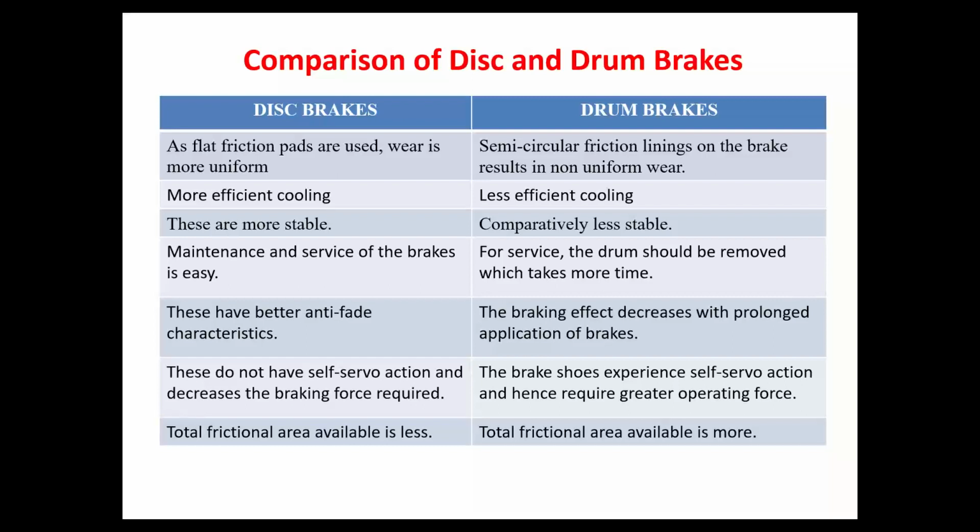Coming to the fifth point, disc brakes have better anti-fade characteristics. Fading we were discussing, which is due to prolonged continuous usage of brakes. Anti-fade characteristics are far better compared to the drum brakes. Point number 5 and point number 2 are interlinked. Whenever the cooling mechanism is better, fading will obviously be low. So even if you are using it continuously, you will not feel any decrease in braking efficiency.